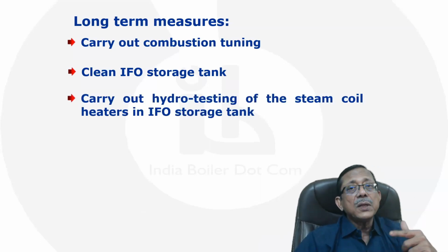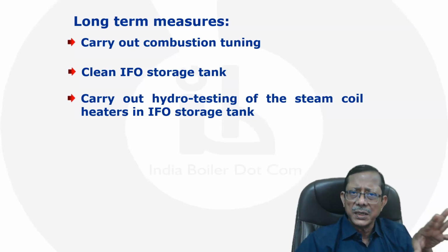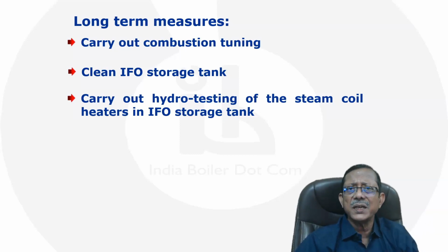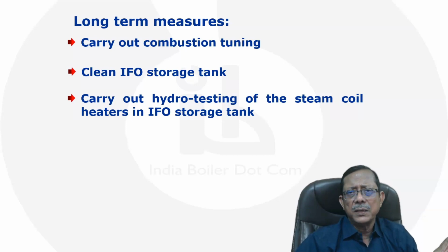They have to carry out the hydro test of the steam coils which are heating the storage tank, because the source of water can be from the leakage of these coils also, because HFO is very corrosive. And the steam coils, which are inside the tank, right, if they start leaking and if they do not conduct the hydro test and ensure that these leakages are not there, then the water can come from the heating activity itself. So they will have to go for hydro testing and maintenance of the steam coils.